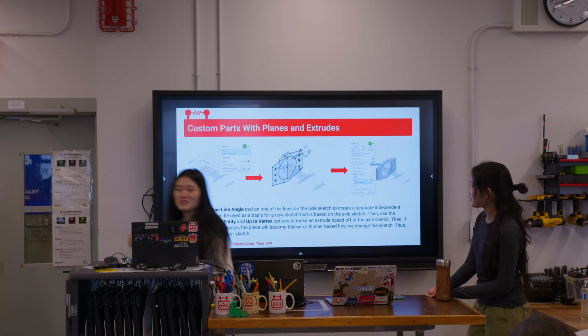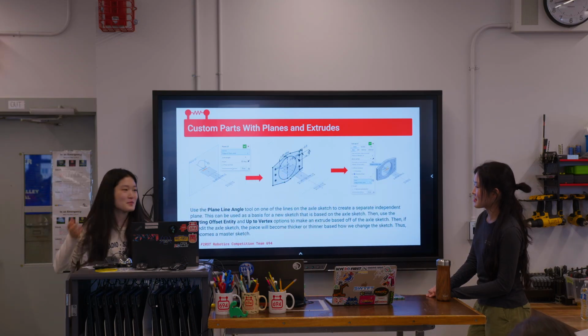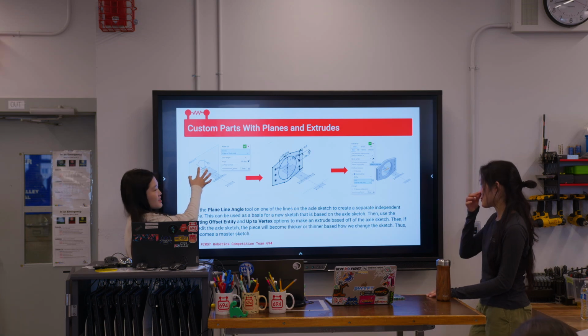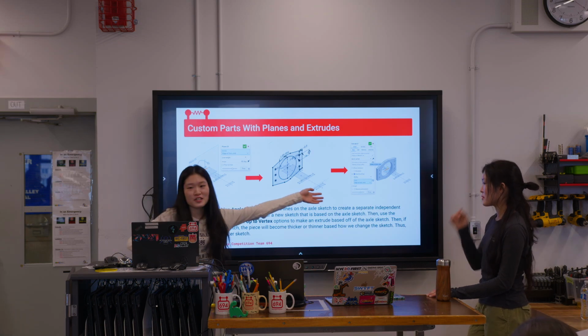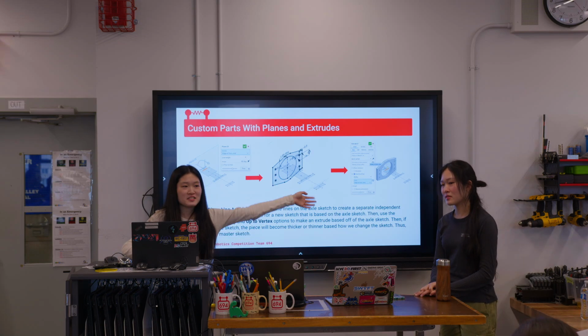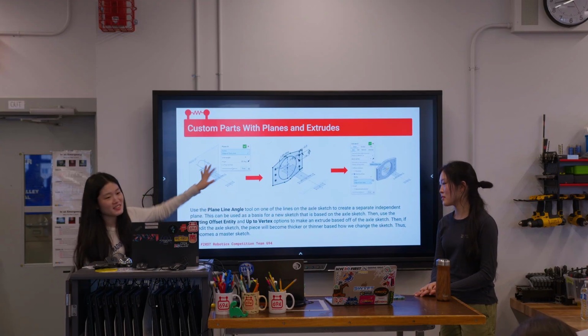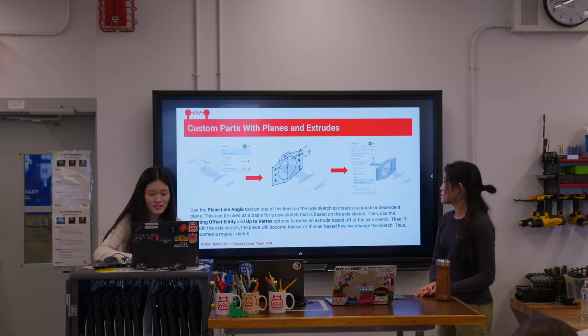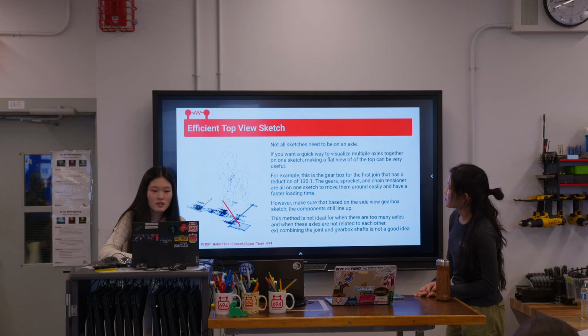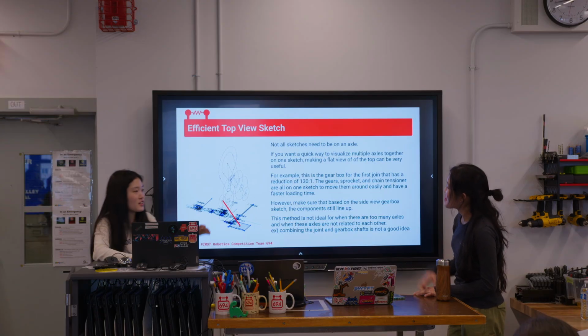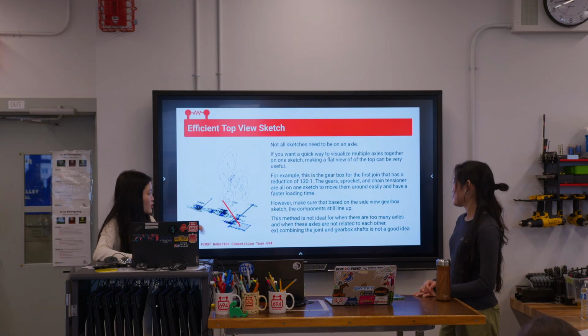Let's say, oh no, 1/4 plate is too thin. I don't know why it would be too thin, but let's say I want to make it 1/2 inch. I just change that on the axle sketch to make it 1/2 inch, and even your extrude will be based on that. So this one sketch can basically control everything. And then what I mentioned before, there's another for the gearboxes.